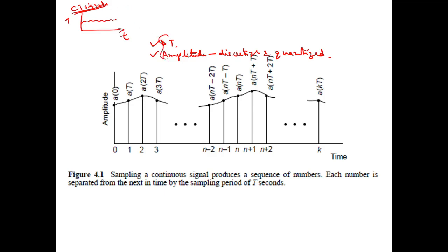So you have the continuous time signals. Now how to make it a discrete time signal? Initially you have to make the signal a discrete time signal. Okay, now how do you make it? You do the sampling of the system. Now when we do the sampling of the system, we basically multiply it with delta train, which we have already discussed in one of our previous classes.